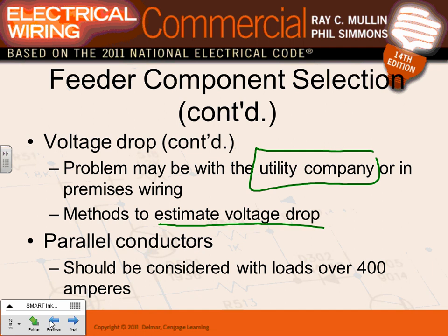So you start with the utilities, and then you have to check your distances on your feeders. 100 feet or less, for the most part, you're good. Higher than 100 feet, check your feeder. So you have a voltage drop, what do you do? If it's 1, make it 1 percent, right? Any questions about this? Any comments, any questions?